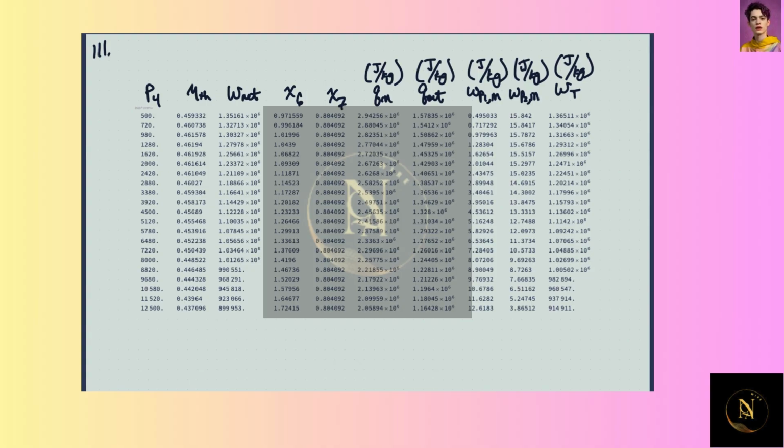We're going to look at determining the efficiency against extraction pressures. These extraction pressures are of various megapascals, going from half a megapascal to 12.5 megapascals. They gave us the specific values to look at, but I just made a loop and went through a bunch of them, to see the effect of the extraction pressure on the performance of a regenerative Rankine cycle.